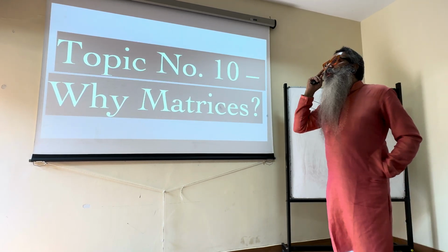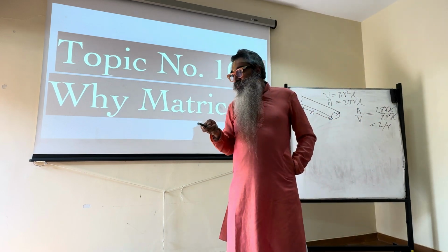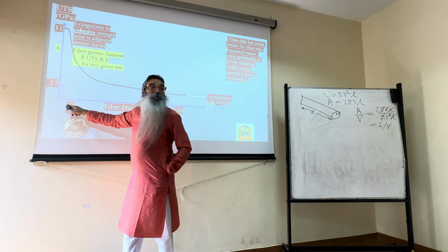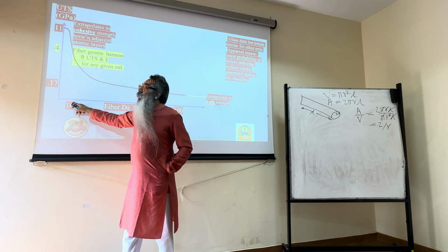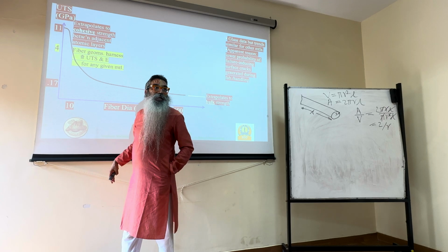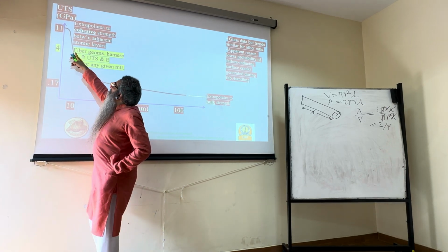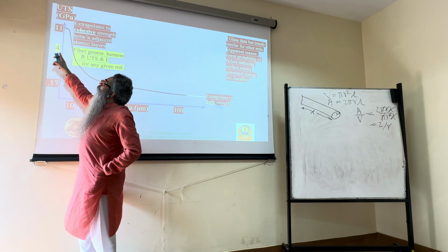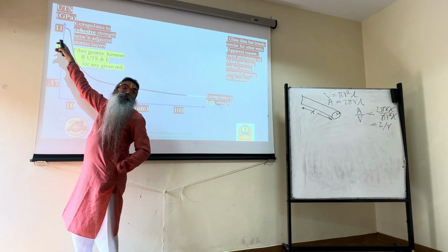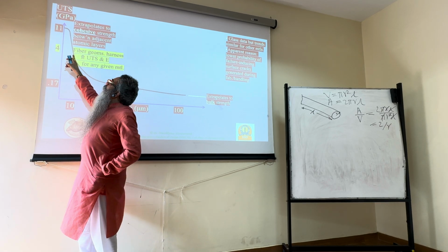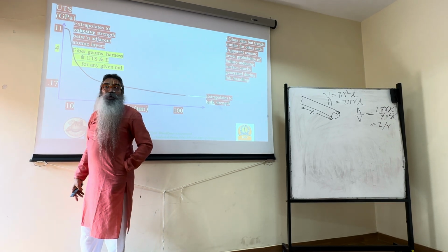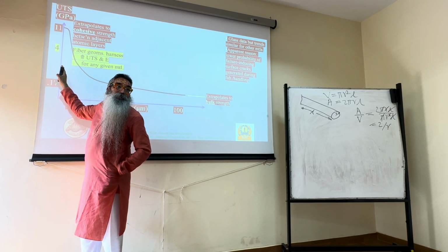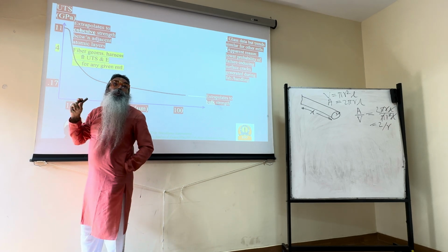Okay, so that answers for us the question of why fibers, because we know that when you have a fiber, especially typical diameters for glass fiber or carbon fibers, around the order of 10 microns, you have at least about 4 GPa. That is what you can get. Even though the theoretical limit is 11 GPa for glass, you can't usually achieve that. You will achieve about 4. If you try to go as close to that as possible from the current state of the art in manufacturing, you get what are known as whiskers.